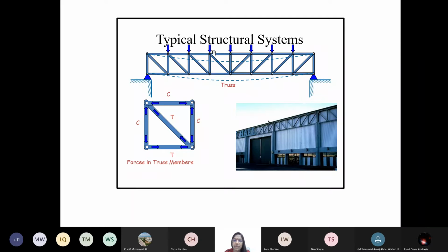To take up the tension only, they put the crossbar. If you remove all these crossbars, they all get bent already, or the compression will be more. To support this compression, they put the crossbar, or to take up the tension, they put the crossbar. Why the crossbar? If it is horizontal, again subject to compression. If the same thing has some inclination, it may get elongated rather than compressed.